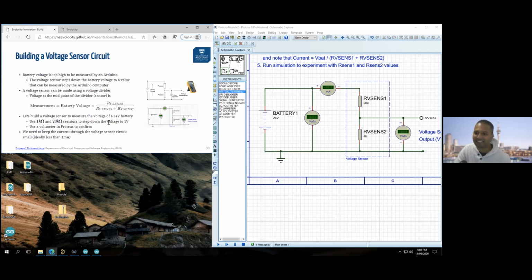Depending on whether you have a lead acid battery or a lithium battery, this can be quite a bit different. You should probably ask Liz. Are you using the lead acid batteries or the lithium batteries in your car? I think Levi will have lead acids here. Okay. Those lead acids probably would go up to about 26 volts when they're fully charged, approximately. Yeah, fully charged they will. And then it'll come down to about 20, 22 when they're fully discharged. With no current on, yeah, probably.